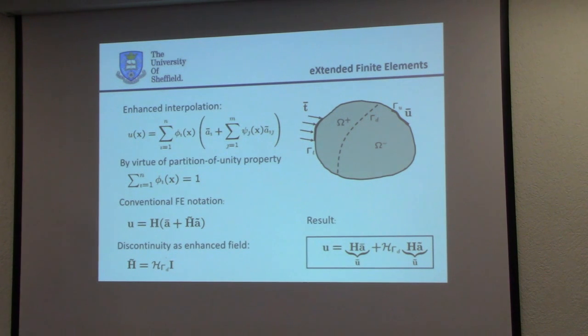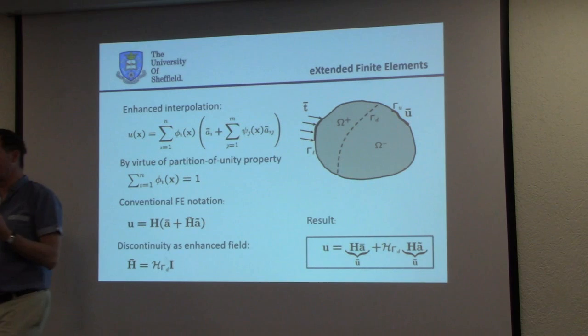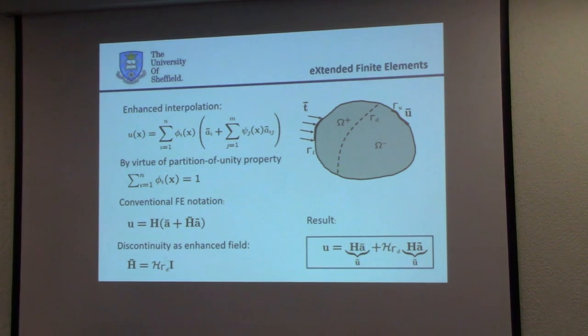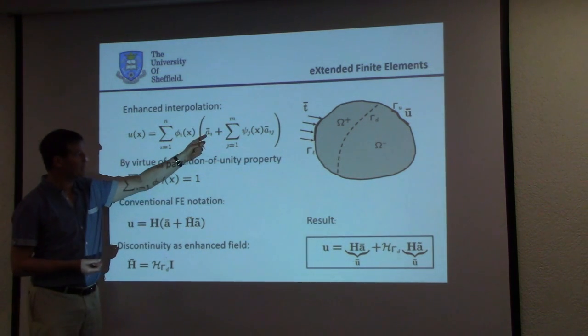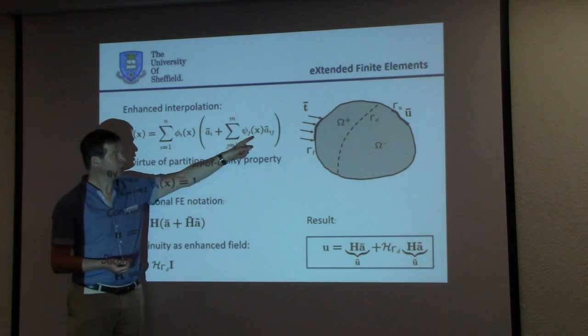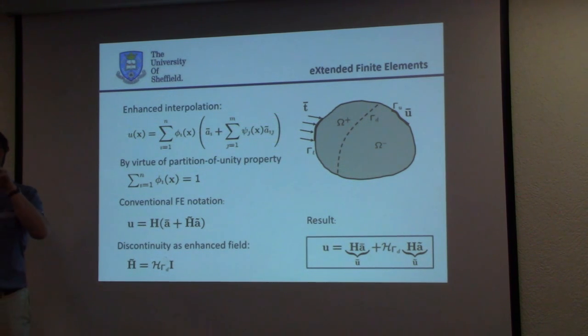Now, what you can do, related to linear elastic fracture mechanics, is that at each node you can add those four singularity functions of linear elastic fracture mechanics. This way you try to capture the singularity, which is very hard to capture using normal polynomials. So at the crack tip, you enrich this by injecting singularity functions.